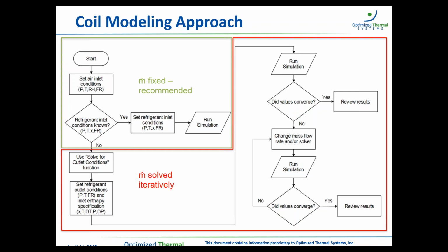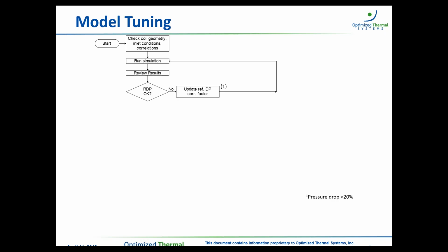So just as a brief reminder, we recommend that we begin with fixed refrigerant inlet conditions and mass flow rate when performing any model tuning. The next slide summarizes a systematic approach for tuning a heat exchanger model within CoilDesigner. This isn't the only way that this tuning can be performed, but it's an approach we recommend because it's consistent, repeatable, and simplifies the process.